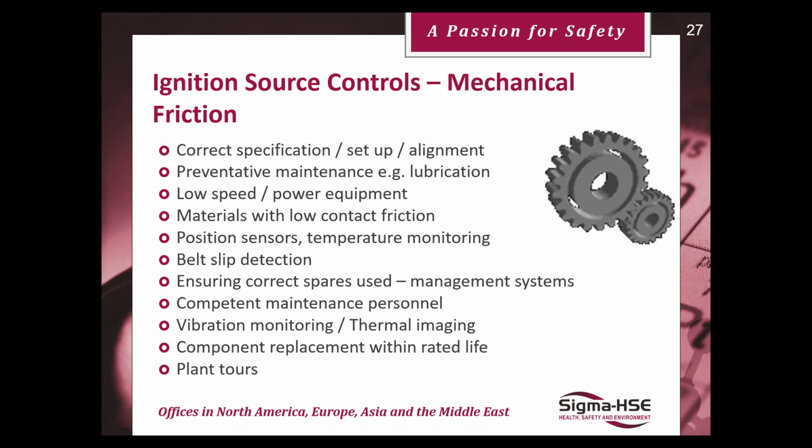So for mechanical sparking, there are many types of safeguards you could have. They could be vibrational monitoring. They can also be inadvertent. There are other sensors that could act as safeguards, but they could be indirect sensors. For example, if you have a screw conveyor, you could have a blockage sensor. Its primary function is to detect blockages, but ultimately it could help in other areas such as hot surfaces. Maybe the blockage leads to a hot surface or mechanical sparking. So yes, vibrational monitoring, component replacement within rated life.